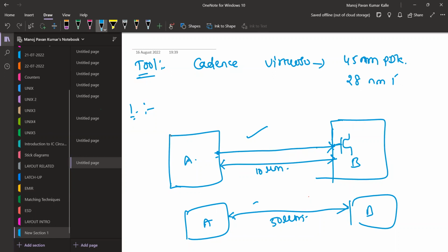If you increase this routing length, then there is one parameter called the antenna effect. If we increase this gate routing length, you will get some antenna effects, so you need to reduce this. All these kinds of techniques are reliability techniques. If you don't consider these things, your chip will not work for many years, because this antenna effect will spoil your entire active gate. So you need to remove all these things. These things come into the layout only, because the designer can't directly say where you will get antenna. It is purely the layout guy's responsibility, and this is one reliability technique.